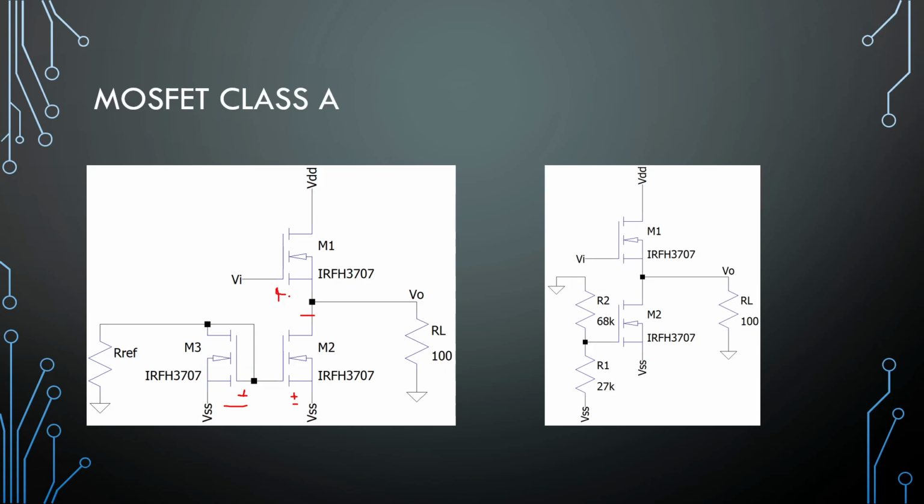We will have a larger offset due to our VGS, but if you pick the right MOSFET, you can have a smaller offset than our BJT. As a side note, if threshold voltage is much lower, you can get away with a smaller offset voltage.